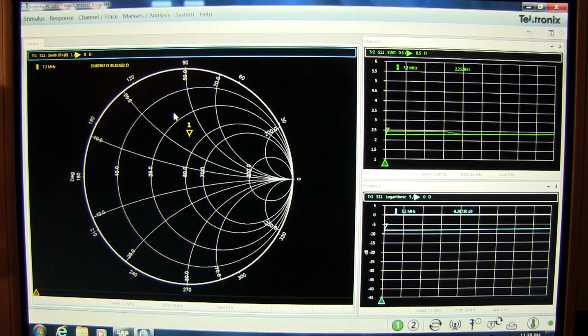Now our goal is to get a 1-to-1 SWR, which will be achieved when the input impedance is right here in the center of the chart, right at 50 ohms resistive. So all we need to do is essentially adjust our controls to kind of get us there. And you can see if I adjust my inductor down, my capacitor back here, and get ourselves really close, if we're really careful here, and zero in to something very, very close to just a 50 ohm resistive termination. And if we look here now, I'm at 49.7 ohms and about 0.4 ohms of inductive reactance. And if we tweak that a little bit more, I might be able to get even closer.